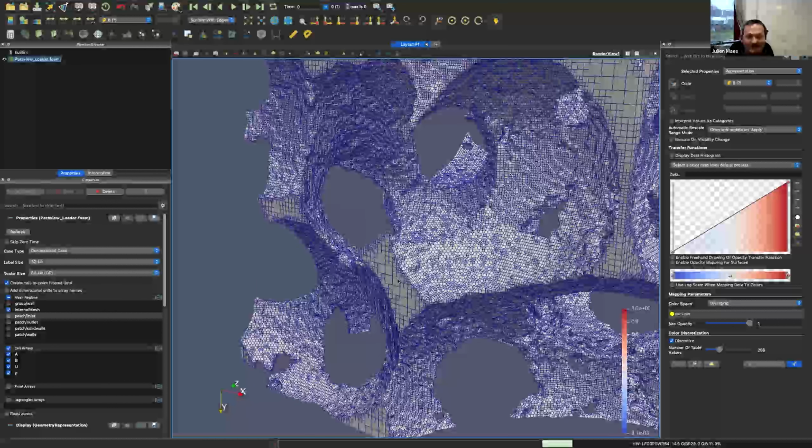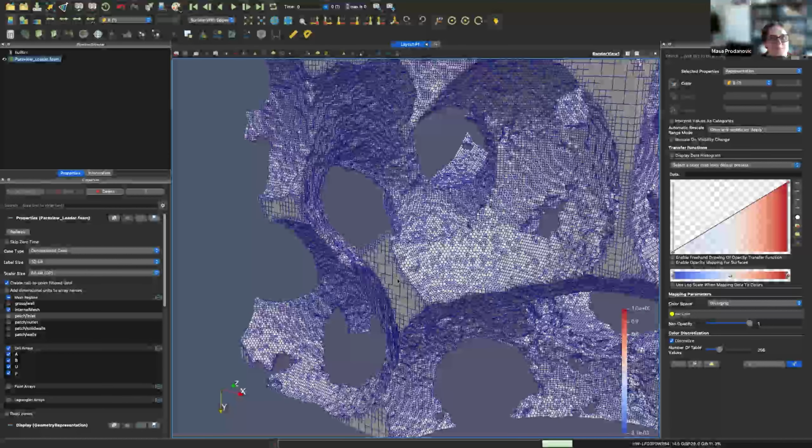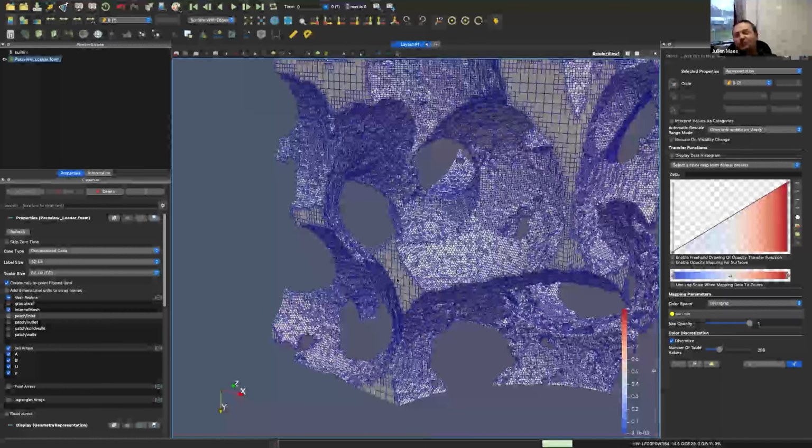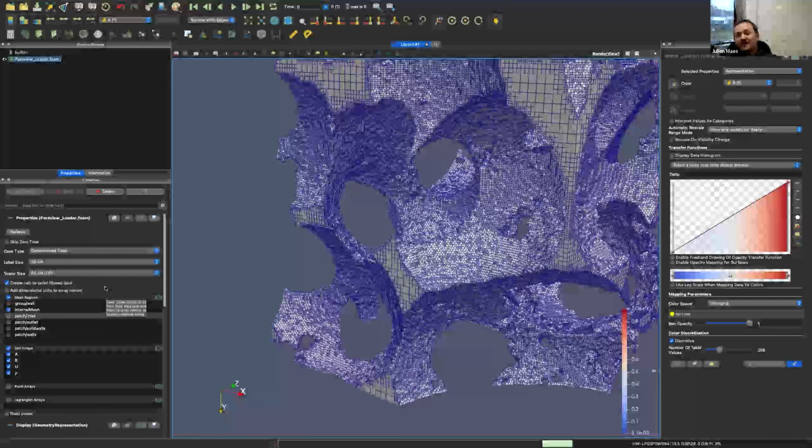It could decide to plot slightly different, because the streamline is numerical. You have a starting point, and sometimes you end up in the wall and go back. But the transport solver doesn't use the streamlines. The streamlines are just a ParaView visual. The transport solver is an advection diffusion finite volume method. It doesn't need the streamlines.